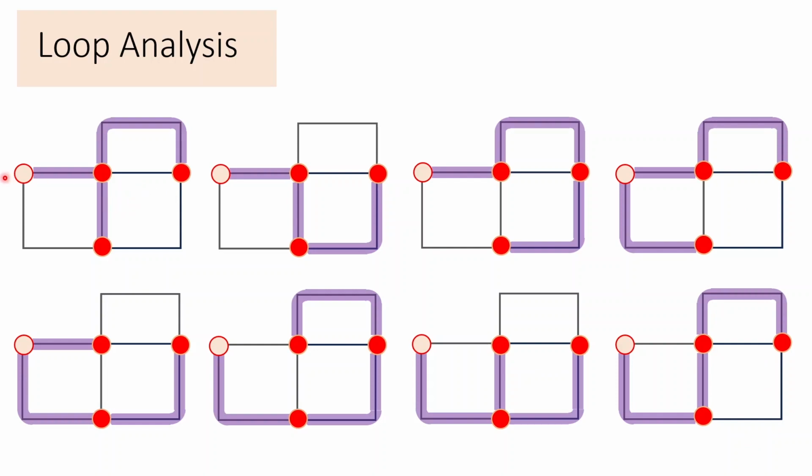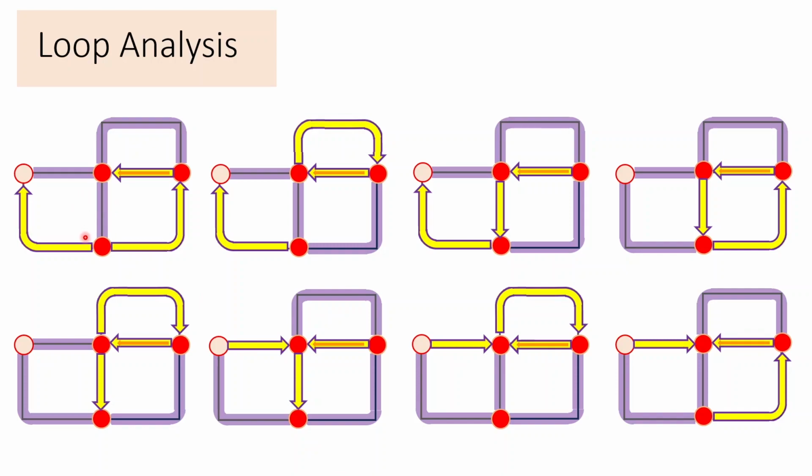It turns out that once we have a spanning tree, the remaining branches are called chords. And a spanning tree is such that it's a set of branches such that from any junction you can get to any other junction through tree branches only. And notice that for the trees, there are no closed loops. And again, the remaining branches then are chords, and you can see we have 3 chords and 3 tree branches, and it is the chord currents that uniquely determine all of the branch currents and the loops that we will be using.